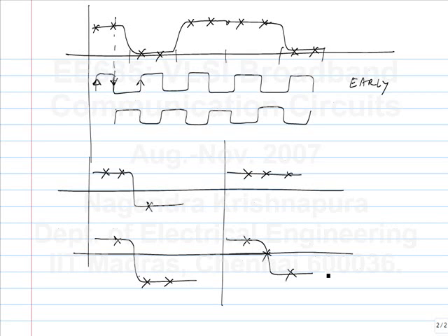So this goes to a flip flop, right? It will not give you 0, it will give you either 1 or -1. There will be some noise and it will steer it to 1 half the time and 0 the remaining half the time. So on average, the contribution because of this will be non-existent.